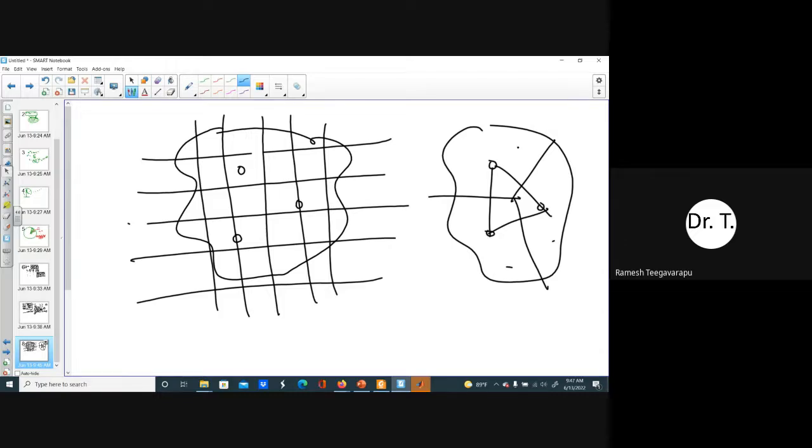But that will not be exactly the same as the gridded data you are getting from radar. So at any level, radar data which is checked with ground truth and has a minimum bias correction, such as a mean field bias correction, puts you in good shape to use it for hydrologic modeling purposes.